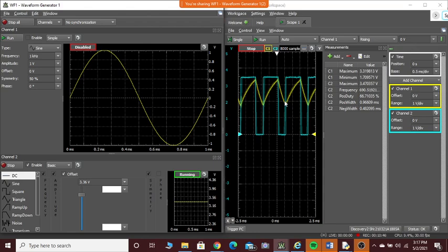What does channel 2 indicate? Output voltage. So in channel 2, you are measuring the frequency, the positive duty cycle, the positive width and negative width. Correct? If I change the voltage, positive width will change, positive duty cycle will change, frequency will change, and of course this maximum and minimum will change. Correct? I will just do the same thing.